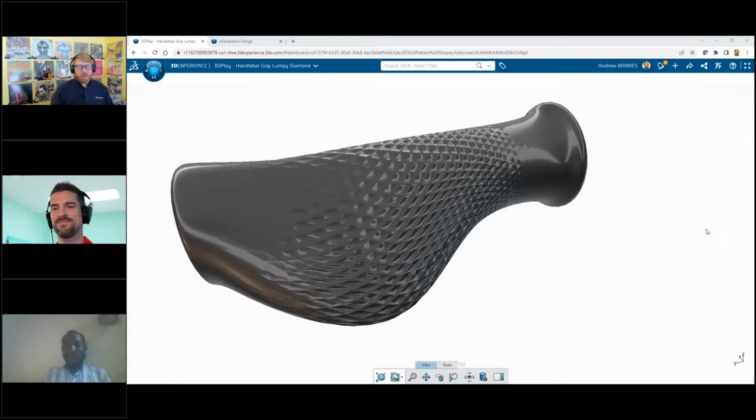Yes, totally watertight. I have never had a STEP file generated in generative design come into SolidWorks with any failed faces. Not to say that can't happen, because you're dealing with thousands and thousands of faces, so it's much more complex than your standard bracket file. So there's a chance for it to happen, but if you have a newer version of SolidWorks and you're using 3D Interconnect, it doesn't even have to do that translation. So it should just always come in as a watertight solid body. That's awesome. Thank you.